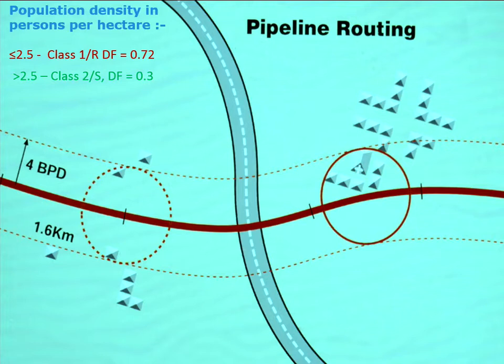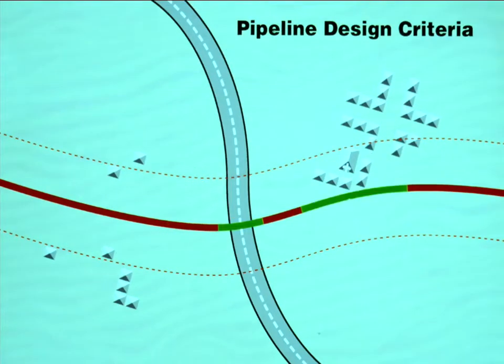So the risk might be unacceptable to the people associated with that development. So you've got to do a survey and identify exactly what's there. You've then got to do a risk analysis, which in this case must be a quantified risk analysis. And you've got to identify risk reduction methods, and you've got to do the ALARP assessment to say, well, do I actually need to apply these?